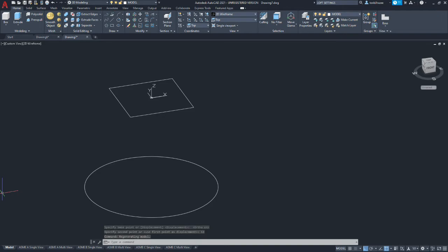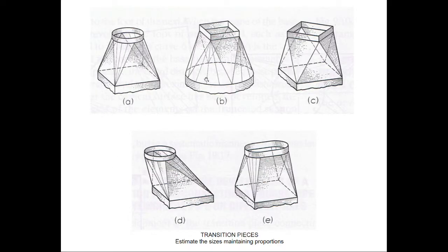Okay, so we're going to look at our loft transition. It's going to be somewhat opposite of the one we just did, but same method. We have flat triangular facets with a large radius here. So we need to make these guide curves that are going to follow these edges.